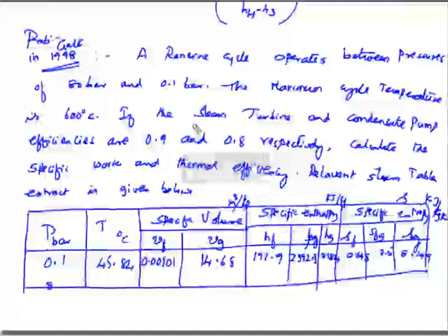Corresponding to 80 bar pressure, the saturation temperature is 295.1, Vf is 0.00138, Vg is 0.0235, Hf is 1317, Hfg is 1440.5.